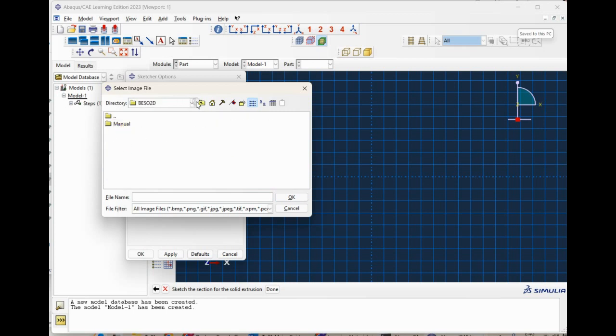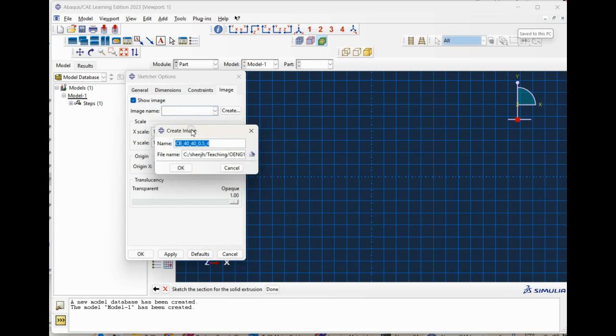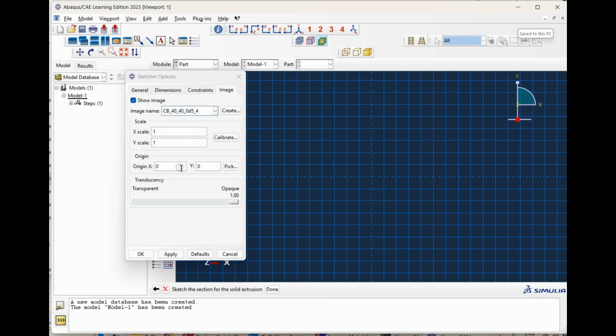TU1, and then that will be it. So remember we resize this one and press OK. It says invalid name. This means it's because the name here can't have a dot in there. I need to delete this dot, or I change the dot with a D. So that will be a valid name. OK. Now I can press apply.